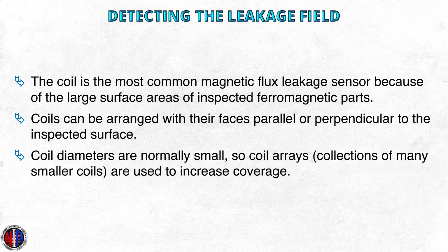Coils can be arranged with their faces parallel or perpendicular to the inspection surface. Coil diameters are normally small, so coil arrays are used to increase coverage. The individual coils in any array might be connected physically or electronically to minimize noise and isolate discontinuity signals.